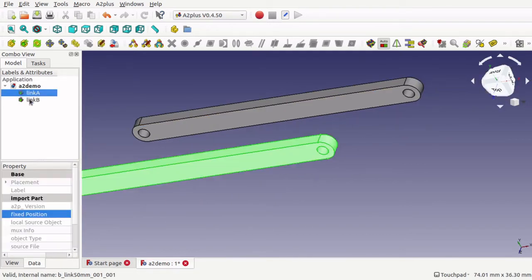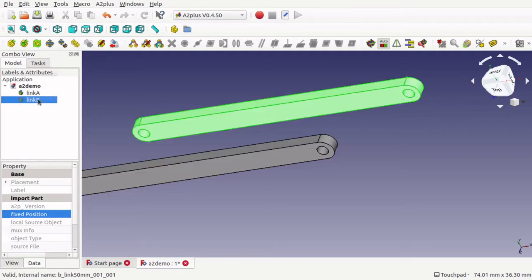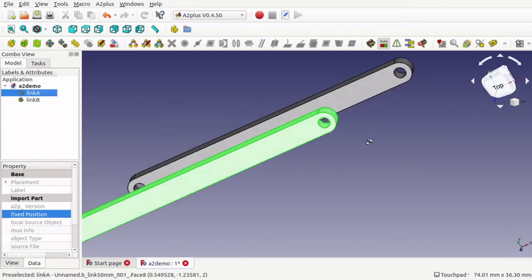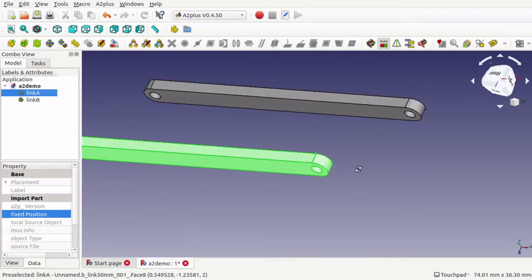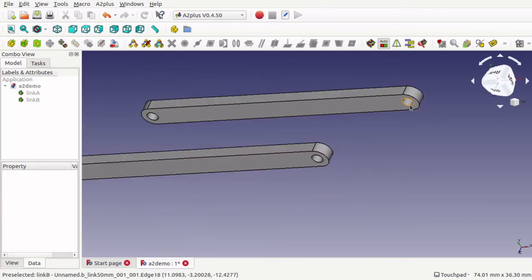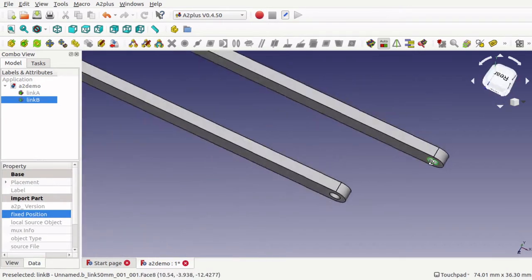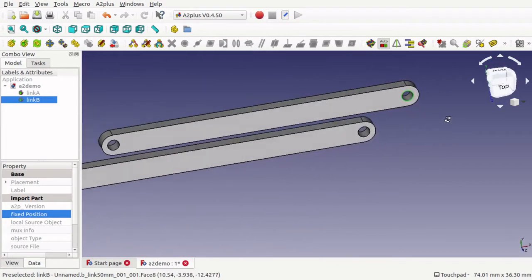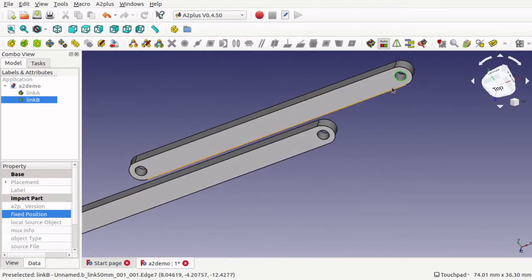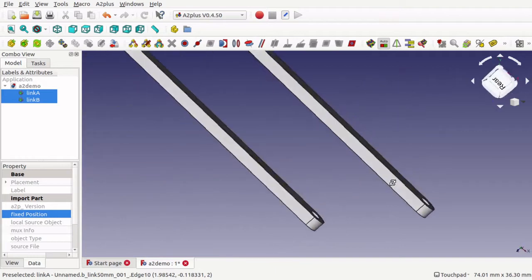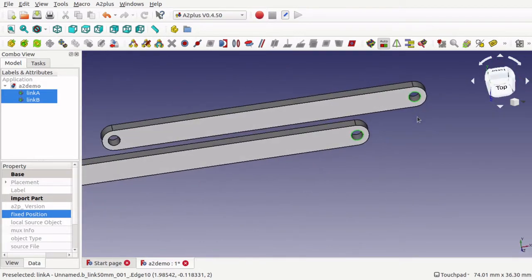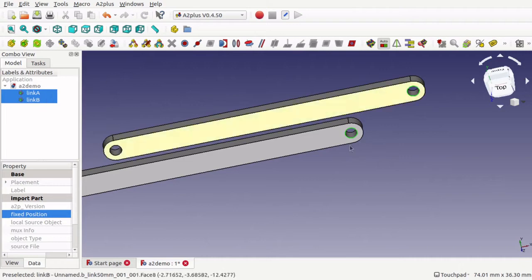So we've got two in here, so if I select those, we can actually see B's at the top, A's at the bottom. And I want to connect this circle. So I've just clicked on that circle and using my Alt to actually move the actual window about. I haven't actually clicked on the actual scene itself, I just clicked on the circle, so that's still highlighted. Hold down Control and select the other circle. So I've taken my finger off Control now and using the Alt so you can see the circles I've selected, and you can see these two are highlighted here.